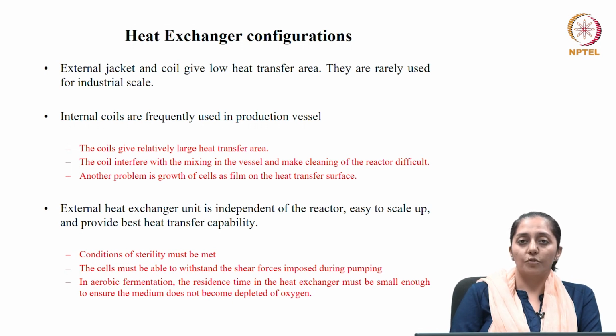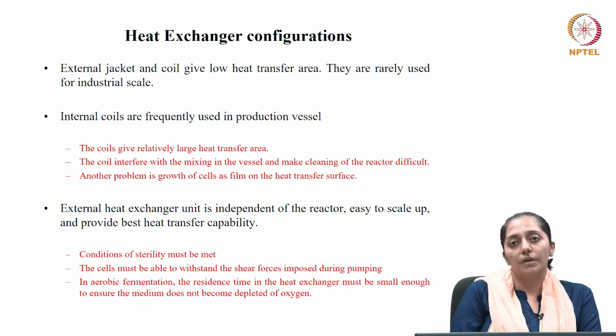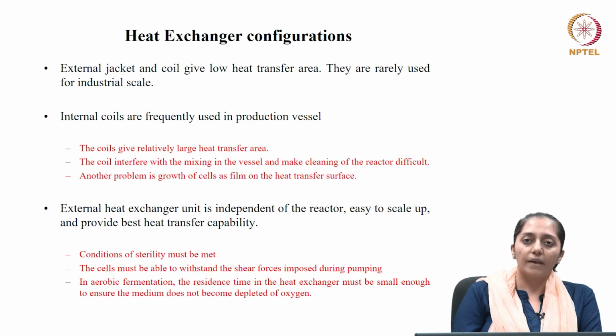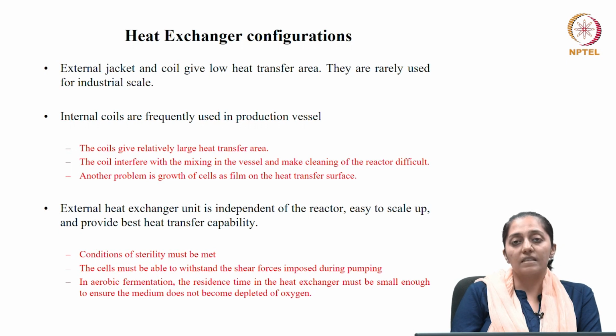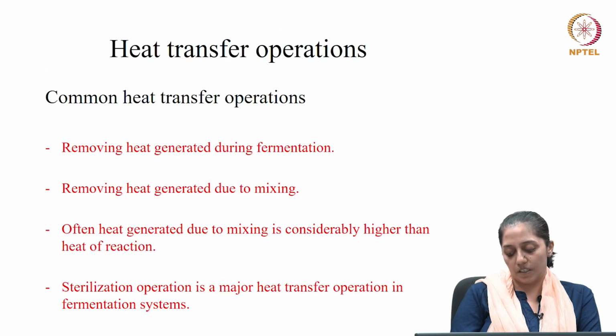The cells should be able to withstand the shear forces which may be induced during the pumping operations to circulate the fermentation medium through the heat exchanger unit and bring it back to the reactor. Especially in aerobic fermentations, the residence time in the heat exchanger should be kept as small as possible, just to ensure that the medium does not become depleted of oxygen during this cooling process or heating process.